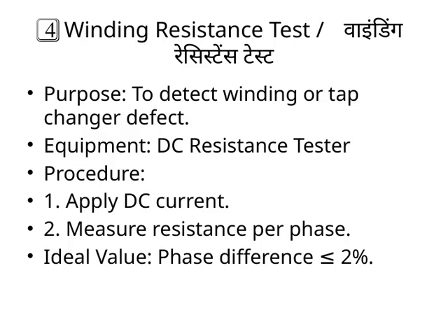So remember, keeping the phase difference within this limit helps us confirm the winding's health and overall transformer integrity. This test is an essential part of preventive maintenance, helping us catch issues early before they escalate into major failures.